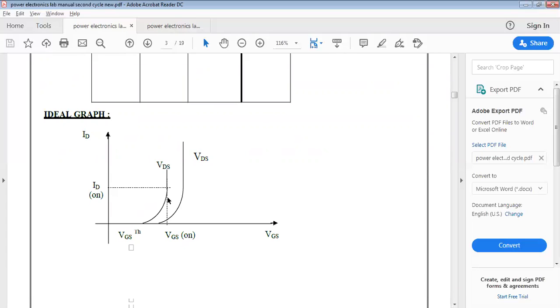With the increase in the supply voltage across the gate to source, you can see that the voltage across the gate to source remains constant, whereas the current goes on increasing, which is proportional to the amount of voltage that you supply to the gate to source, keeping the voltage across the supply, which is powering the load, constant. So this is the first characteristic.